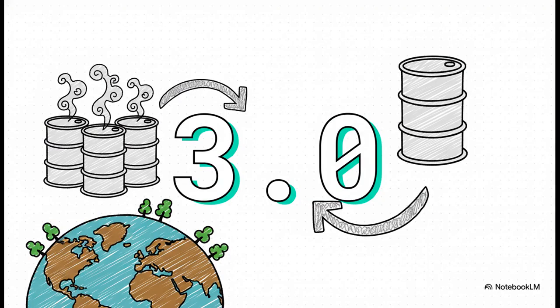So what's a typical number for this? Well, it definitely varies, but a standard industry average for SOR is about 3. Now, just think about that for a second. For every 1 barrel of oil that comes out of the ground, 3 barrels of water had to be boiled into high-pressure steam. This ratio, this is the absolute heart of the entire energy equation.